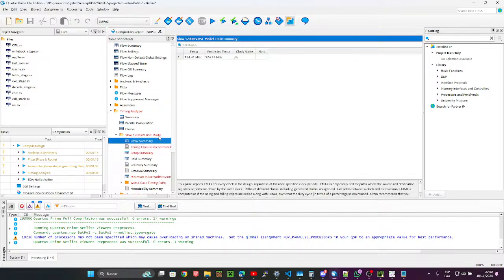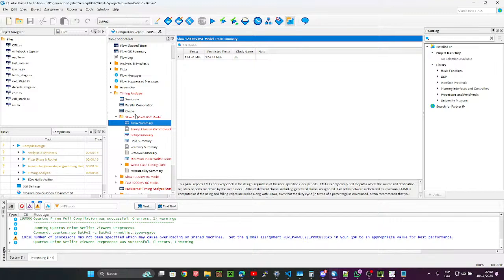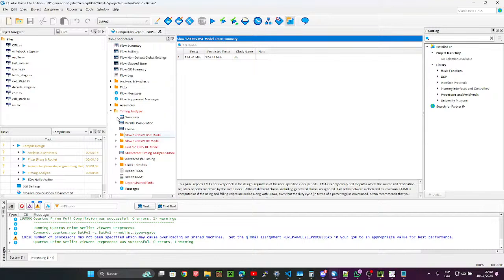It needs 1 megahertz on the other input to be satisfied, right? That means, because you have a divide by 2 in there, the input of the divide by 2, and by consequence the output of the PLL, is now 2 megahertz. You didn't double the frequency, you just told it, generate me a frequency that's double this one.